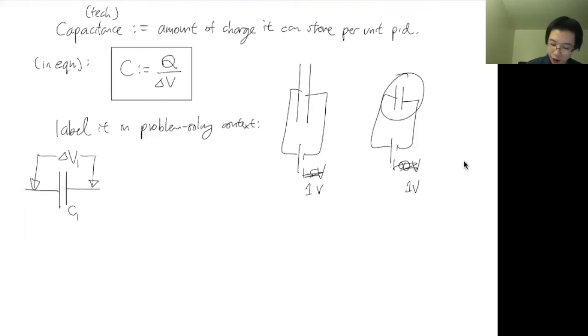And on a resistor, just to mirror this, you can label each resistor R1 and label each of them with the potential difference across them like this, right? Just like a resistor, the most dependent thing is the current. So the current I1 that flows through it is dependent on the potential difference across it and what the resistance is. If you have a small resistance, then there'll be a lot of current. If there's a large resistance, then there'll be very small current flowing through it.